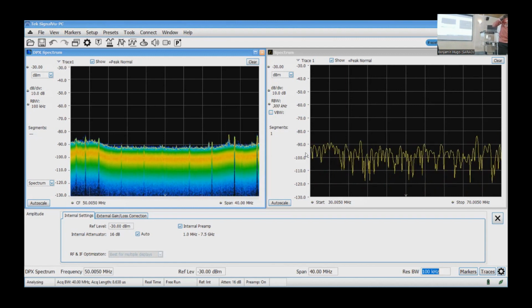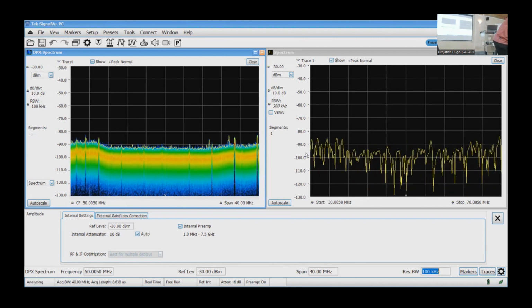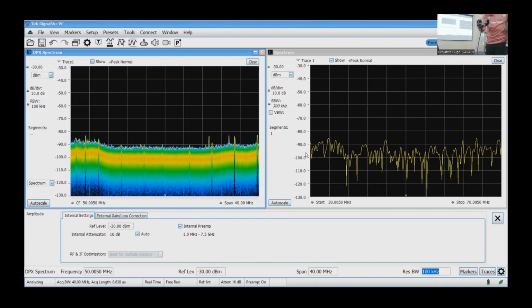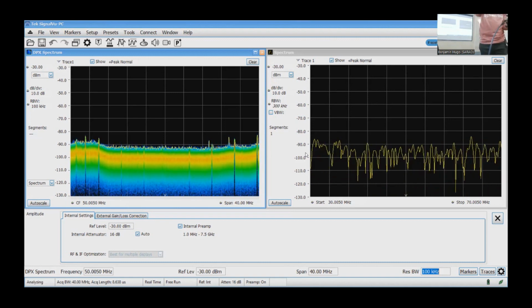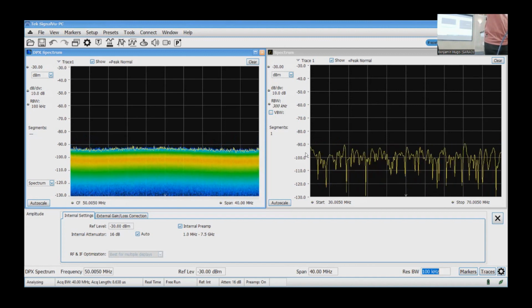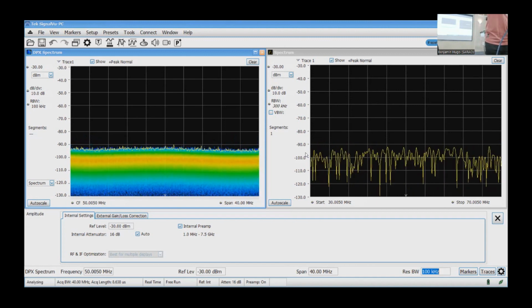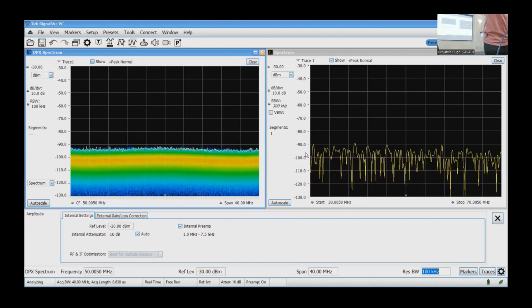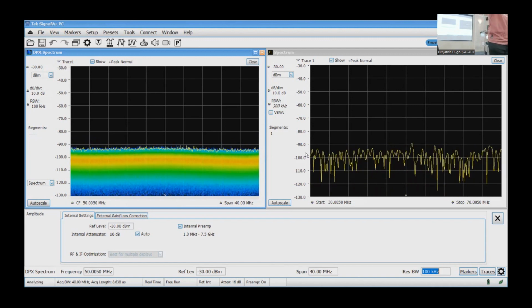But this is a signal cable, so you expect that it is probably a better managed cable. I can go all through and identify which laptop, the poor cable, not well connected, or is picking up a lot of radiation that leads to common mode current on this, just using this guy. And then you analyze that.